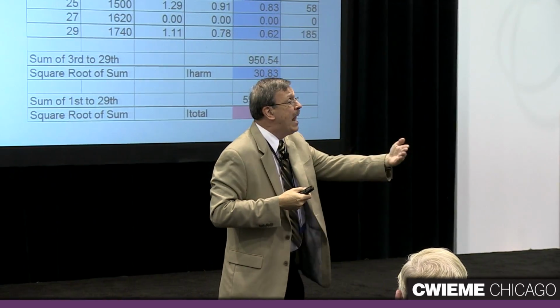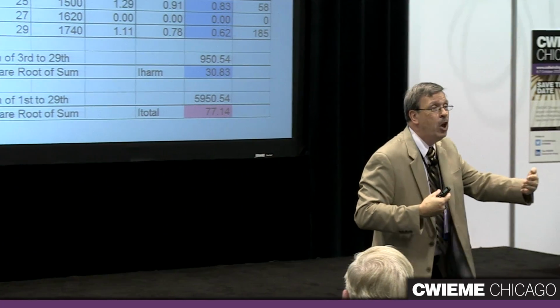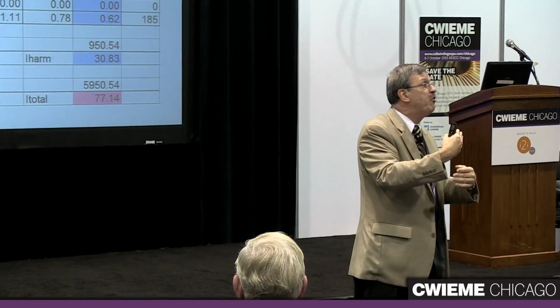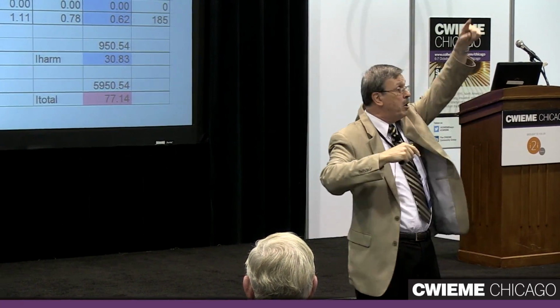So we have about 30 amps or 31 amps of harmonics. We have about 70 or 71 amps of that fundamental waveform. Remember, that's the one that had a peak of 100 amps? And now, when we add those together, what's the RMS value of that red waveform? Again, you don't take 30 and add that to the 70 and it's 100 amps. You have to do the square root of the sum of the squares again. And so we can do this ourselves here.